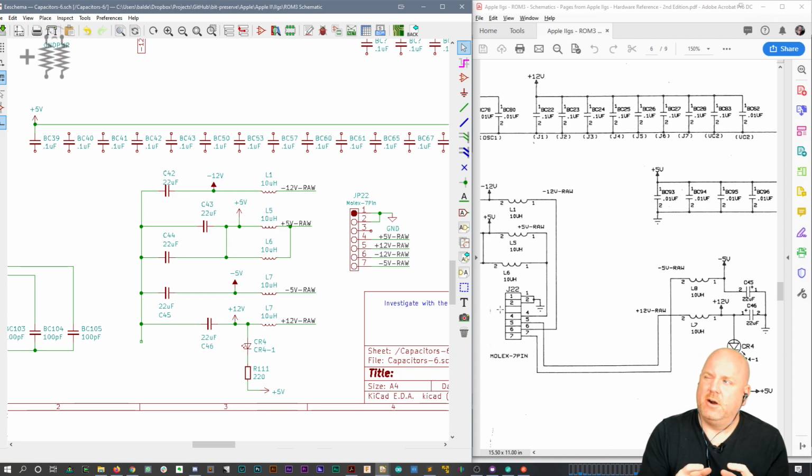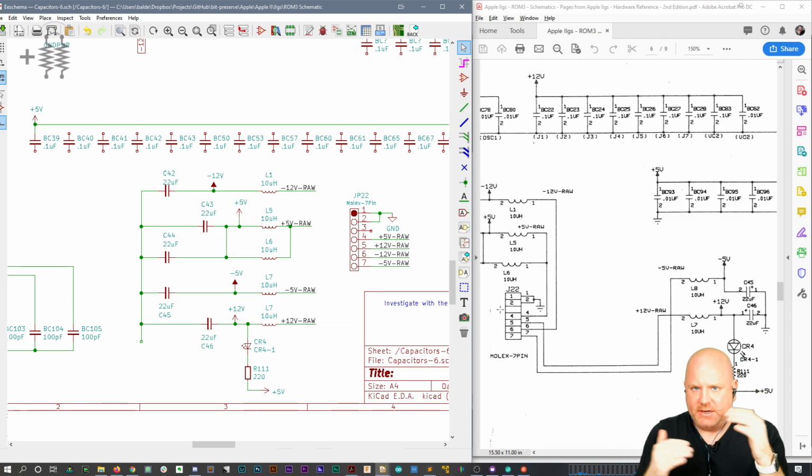I'm trying to think how far I want to go with this. My original goal was to create a cheaper cal standard for the FPC, because the one that R&S wants you to buy, even the passive one, is like $600 or $700. What I don't understand though is the way that the FPC does its calibration. It has to have a specific electrical length, and in the correction factors, you can't specify a different length.